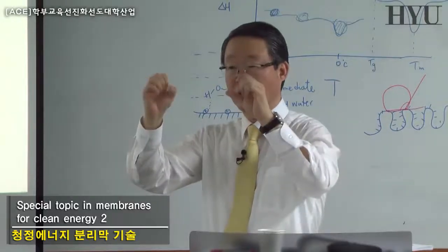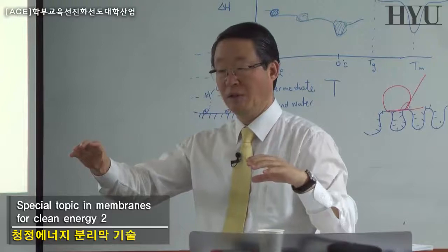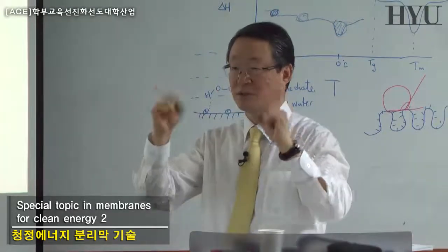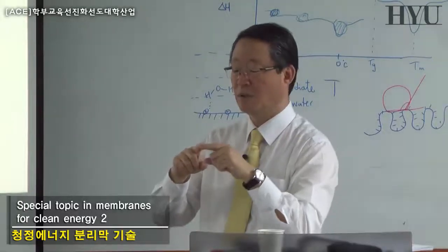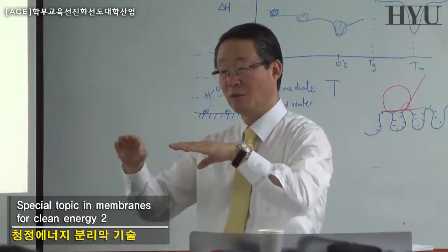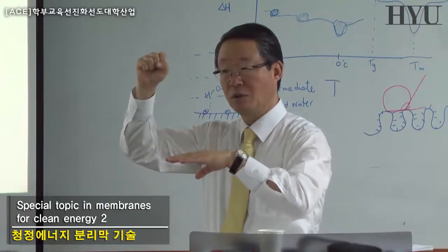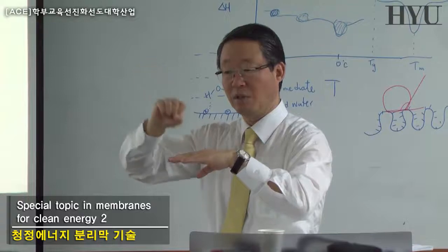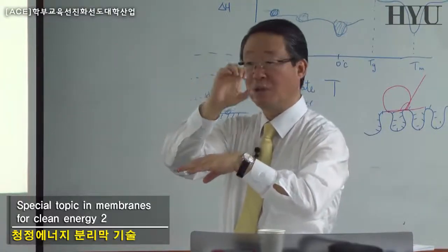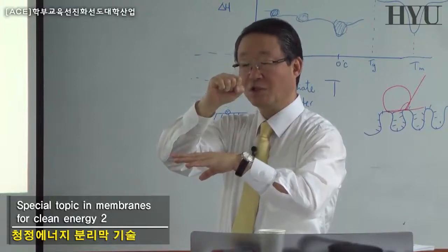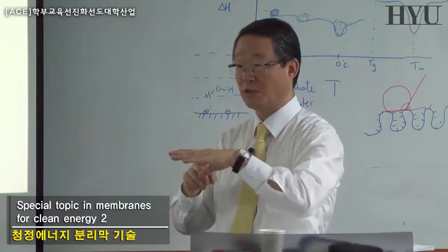with a non-ion-containing polymer, you can neglect the ion effects, whereas if you have ions on the membrane, then there are very complex interactions. If you have a negatively charged ion on the polymer, then a negatively charged ion in the solution may experience repulsion, whereas a positively charged ion in the feed will be attracted to the negatively charged sites in the membrane itself.